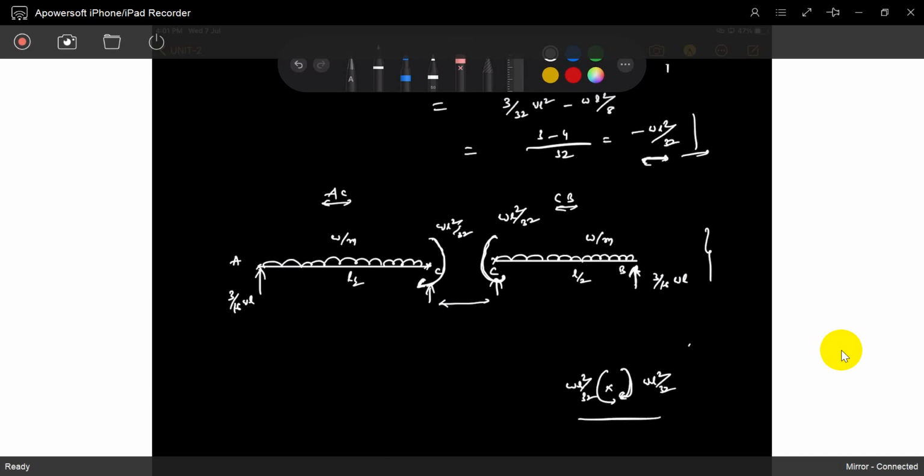So now if you see, it is self equilibrium. Its moment is 0. So that's why, in any bending moment diagram, you can come from one side or come from another side. Both will give the same answer. If you come from this side, it will give some bending moment, and if you come from this side, it will also give the same bending moment, but in different directions. Exactly, that is the moment at that location.